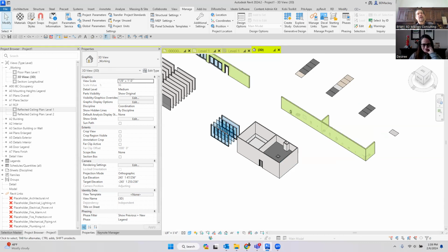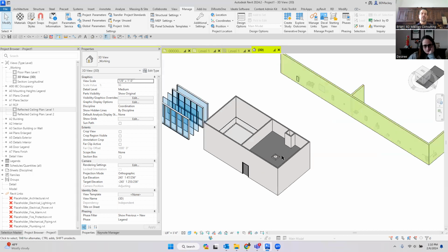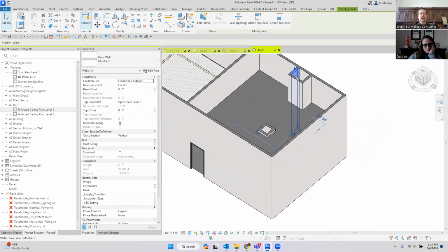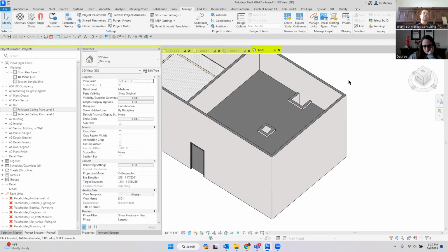Cool. So that's really all I had to talk about. Just one of those things. And I think it was Tom who'd asked for other ideas for global parameters. Like I said, for me, I use them quite often in projects as we get into them and start working. It just depends, we have to remember to set those up. If somebody wanted these other 3 walls at 9'6", and they forget to associate it to the global parameter, obviously that one's not going to go up with it.